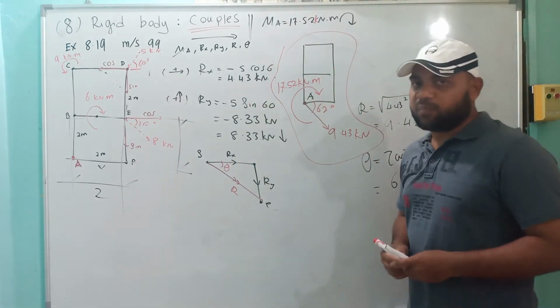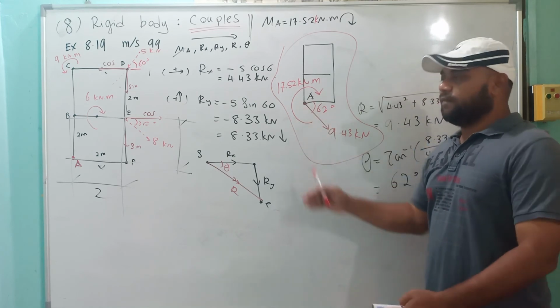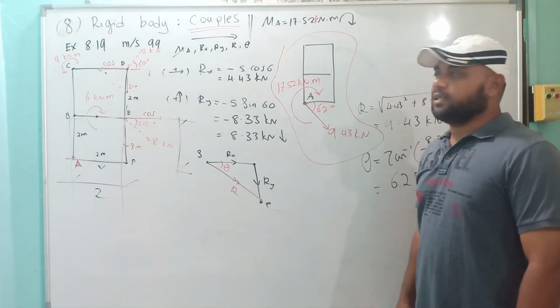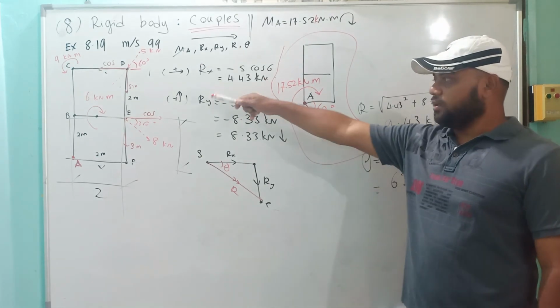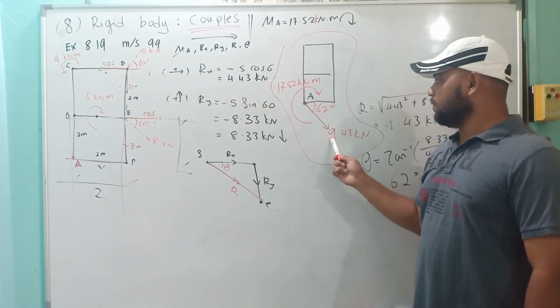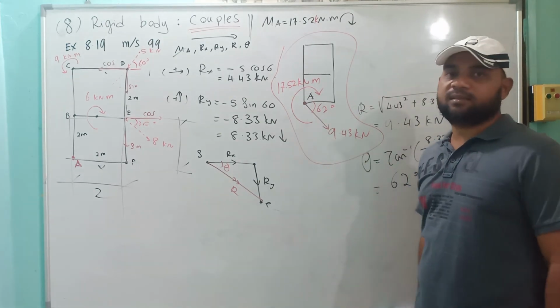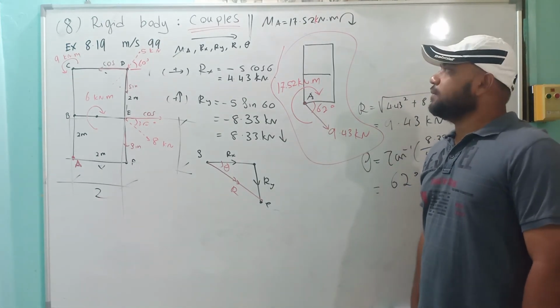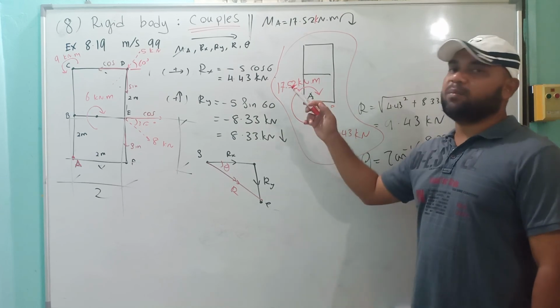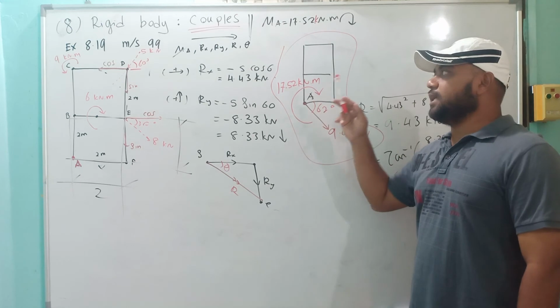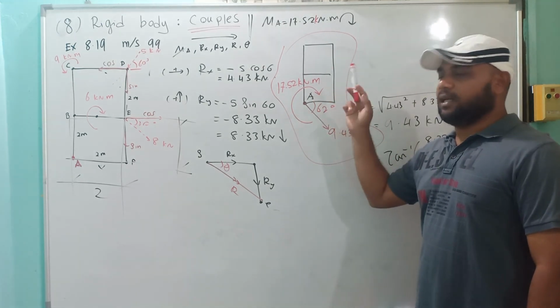Redraw that point A. If the component is not complicated, you just redraw everything, and replace all the forces and moments with only one force and one moment, which is what we already calculated. So your steps are: first calculate the moment at the point the question asks, and then Rx, Ry, R, and theta.